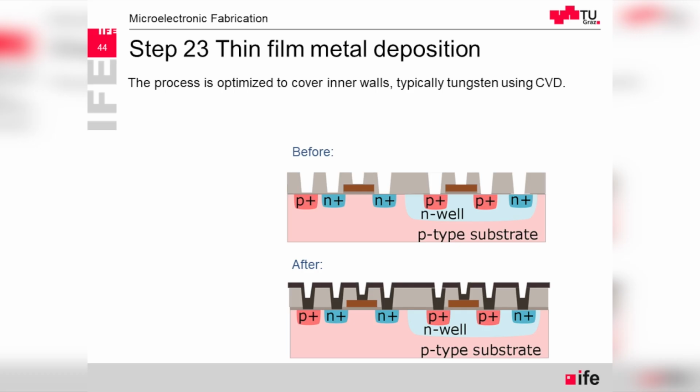And we don't just fill it in with metal, because that might not work well. First, there is the liner. It has several functions. So first, this will be the type of metal that will have low diffusion properties and will be unlikely to diffuse deeper into the surface.